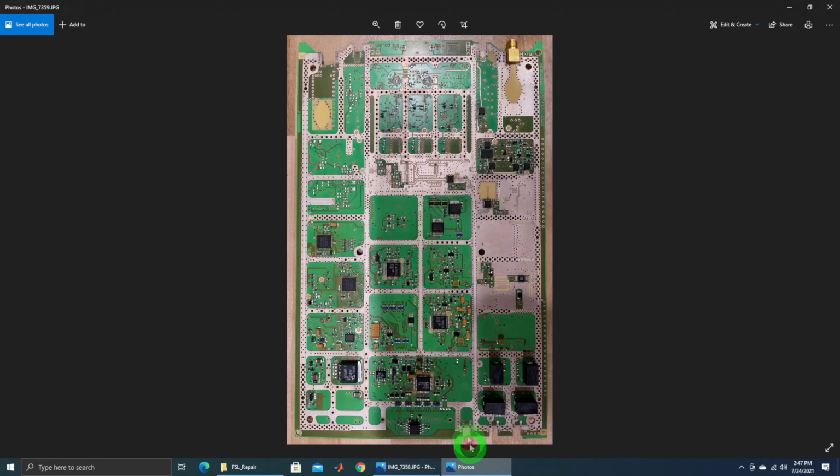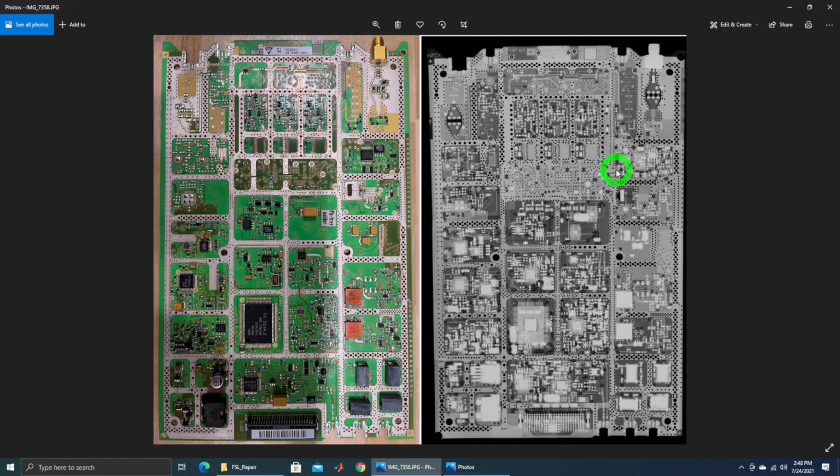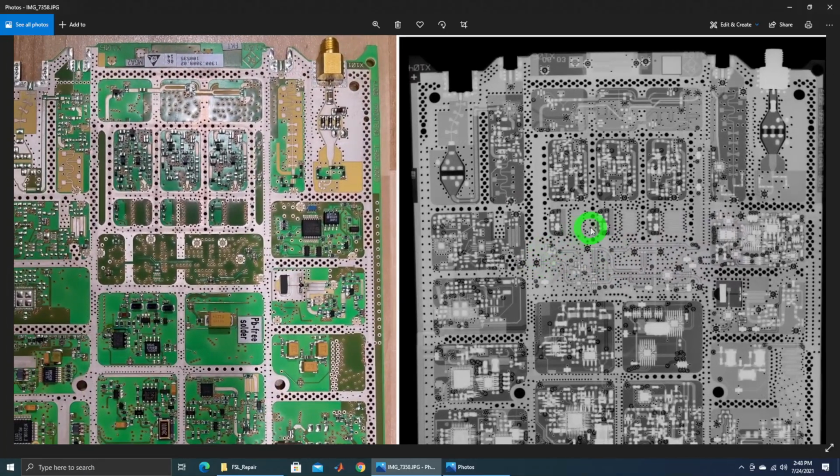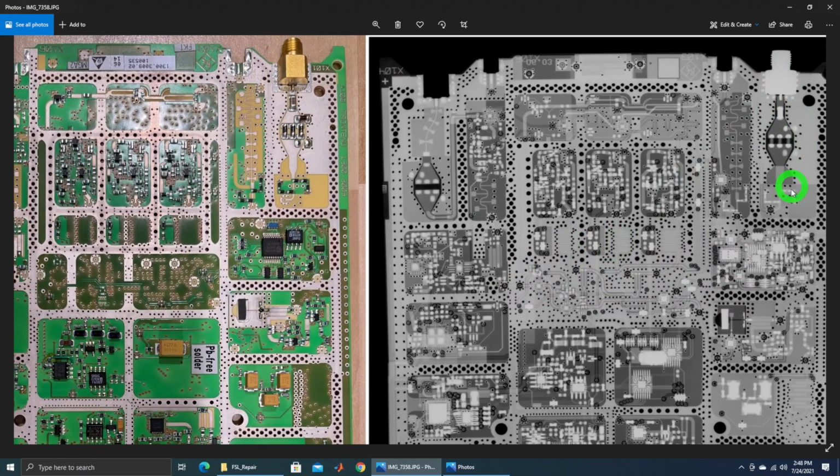And here's the picture of the other side of the board, lined up with the one, so we can really understand what's going on and what's connected to what, which would help to figure out what the issue is actually. So let's look at the front here. You can see the signal coming in, and indeed it does wrap around and goes through this front-end filter. And this filter is a low-pass filter up to 6 gigahertz, eliminating anything above 6 gigahertz so that it doesn't fold back onto the IFs of interest.